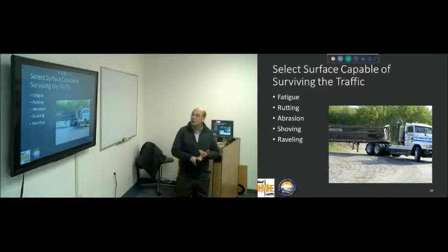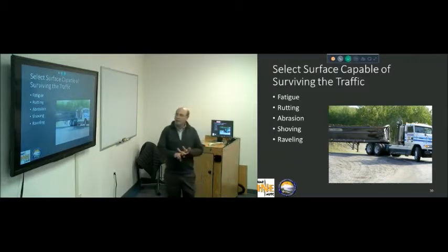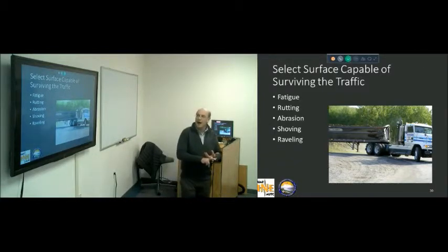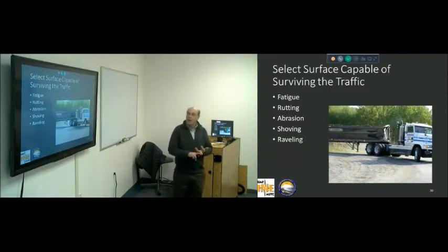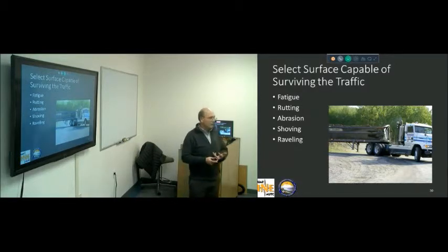All of those come into play. The other part of rutting is due to abrasion due to studded tires. We'll talk about it in a minute. We're implementing a hard aggregate policy to try to get past that one. Abrasion can come not only from studs, but it's just simply the tire wear that's going across it.